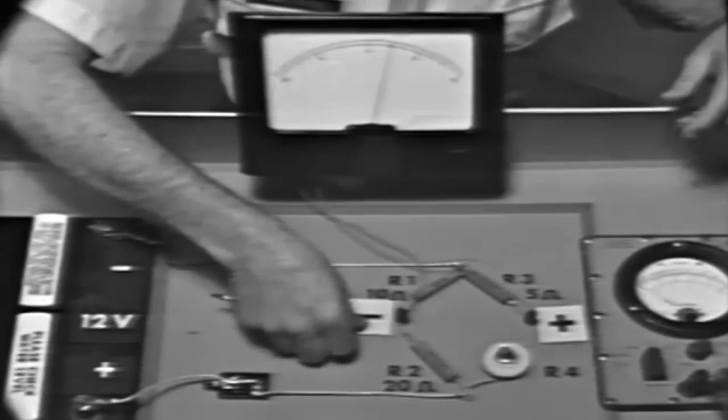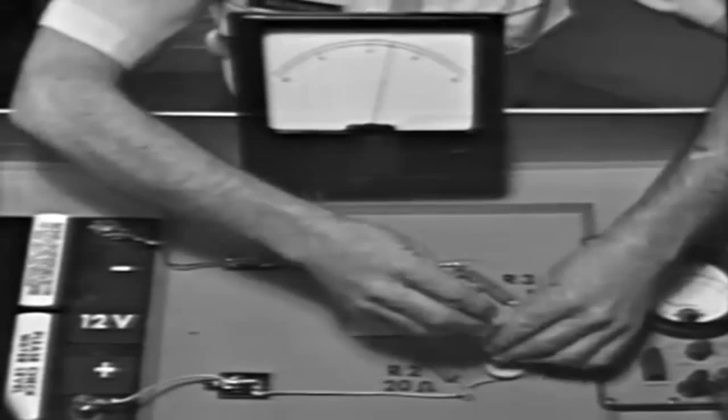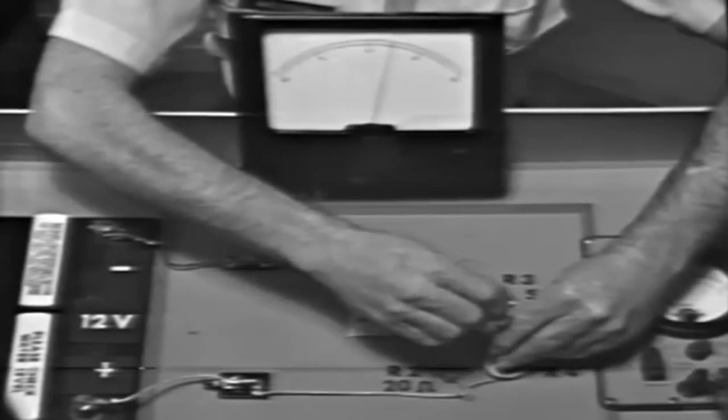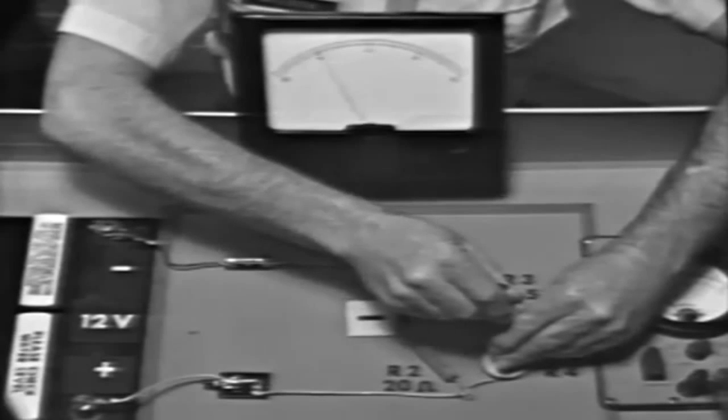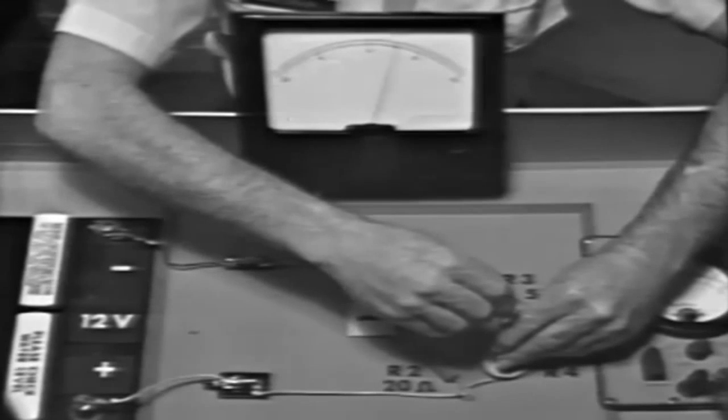This point is now positive with respect to this point. So notice then that with a single control, this rheostat, we can cause current to flow in either direction across the bridge. And of course, we can vary the amount simply by upsetting the ratios more. Now, this feature of the bridge circuit makes it extremely valuable in applications such as weapons control systems, antenna positioning, measuring devices, and systems where a highly sensitive control circuit is required.